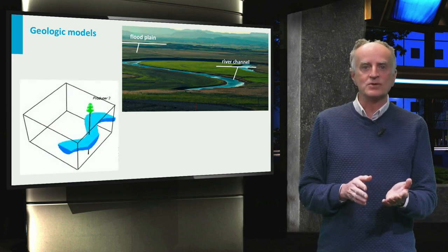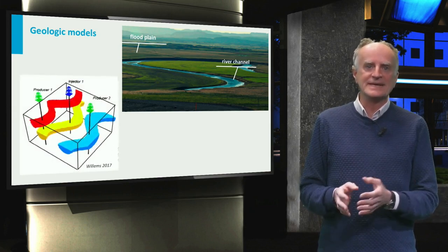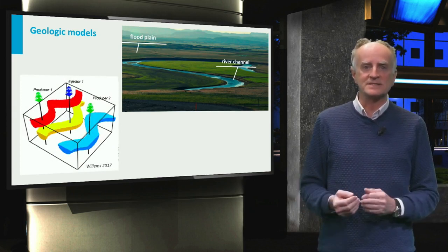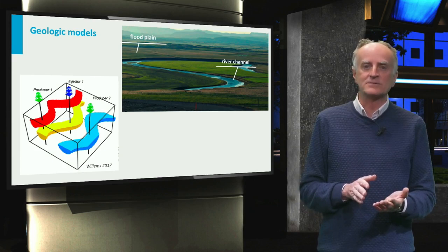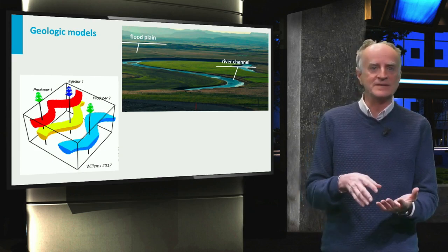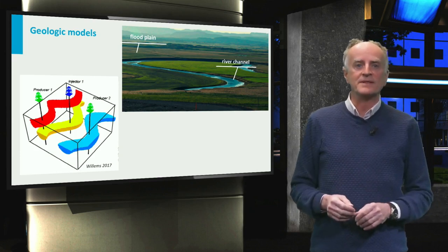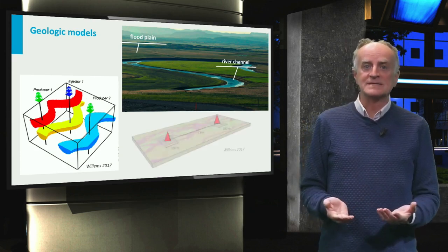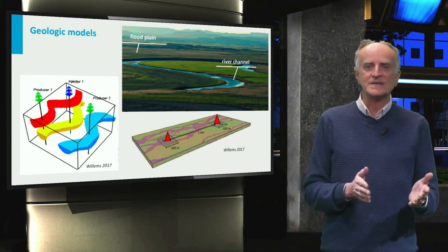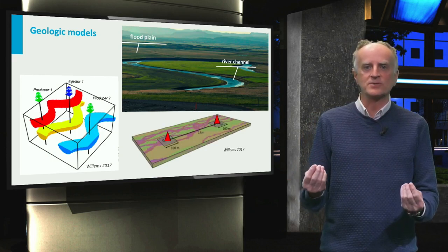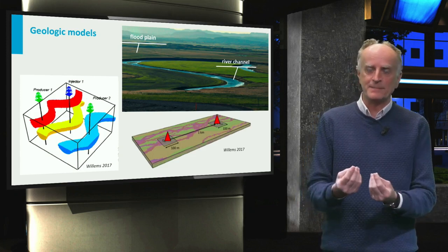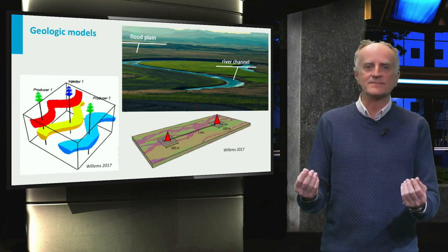In the first step, a geological model of the target volume is built, integrating data from wells with sedimentological knowledge of the relevant sedimentary system. In the second step, physical properties such as permeability and heat capacity are assigned to the different sedimentary bodies forming the model. The model is then ready and is used for a large number of simulations. These include testing the position of the injector and producer wells with respect to the sedimentological heterogeneities and identifying the best distance between these wells.